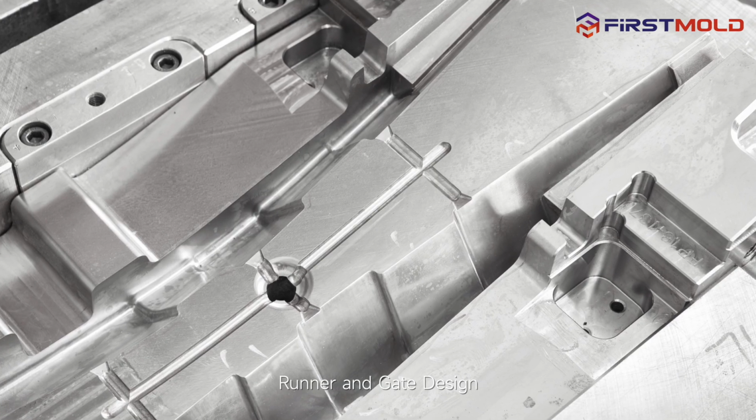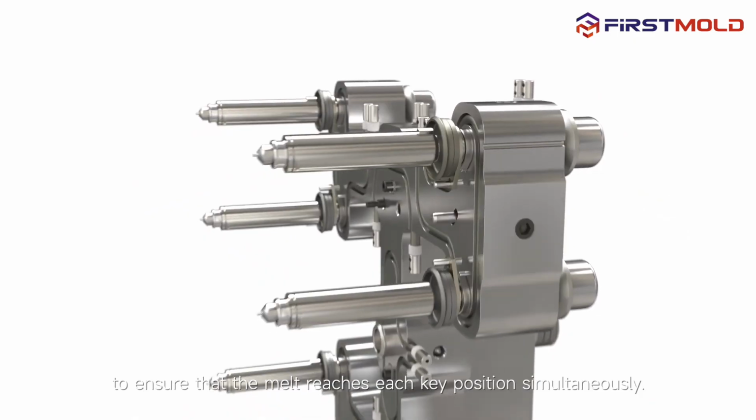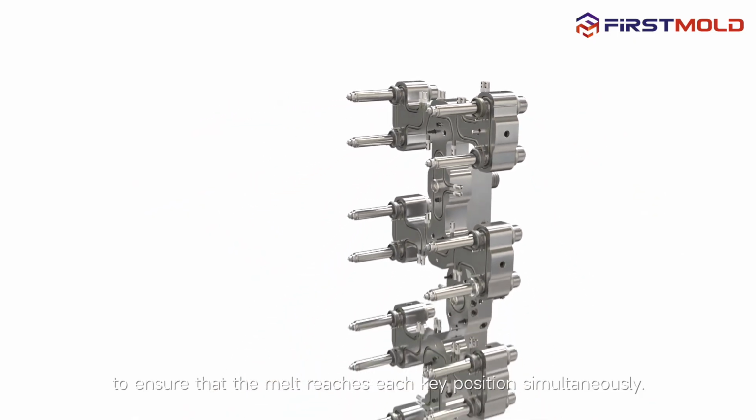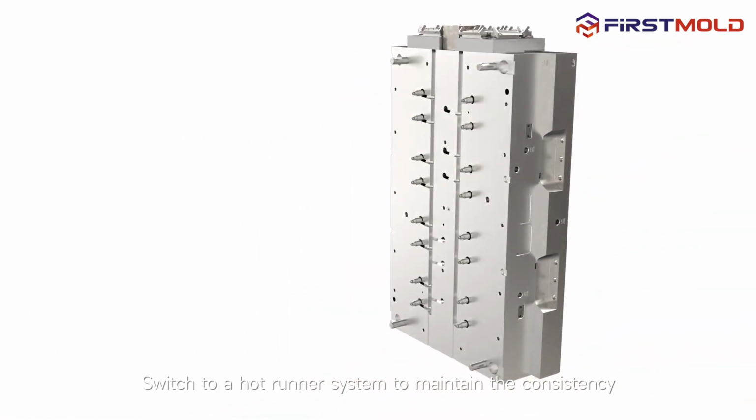4. Runner and gate design. Optimize the runner design to a balanced Y-shaped distribution to ensure that the melt reaches each key position simultaneously. Switch to a hot runner system to maintain the consistency of the melt temperature and reduce weld lines.